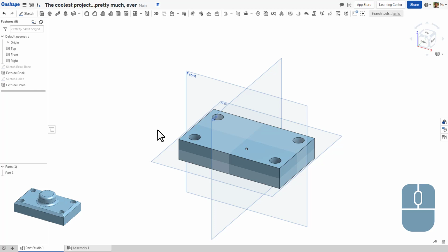If that's the case, let's think back to our earlier discussion at the beginning of this module. What is a different way to create a three-dimensional shape that is not a linear extrusion? A revolve, right? What is the profile of a cylinder when it's revolved? It is a rectangle, right? The side view of a cylinder is a rectangle. So, let that inform our sketch selection.